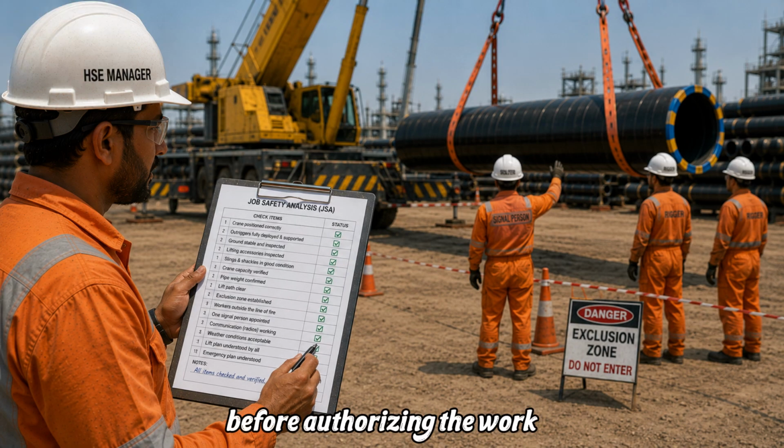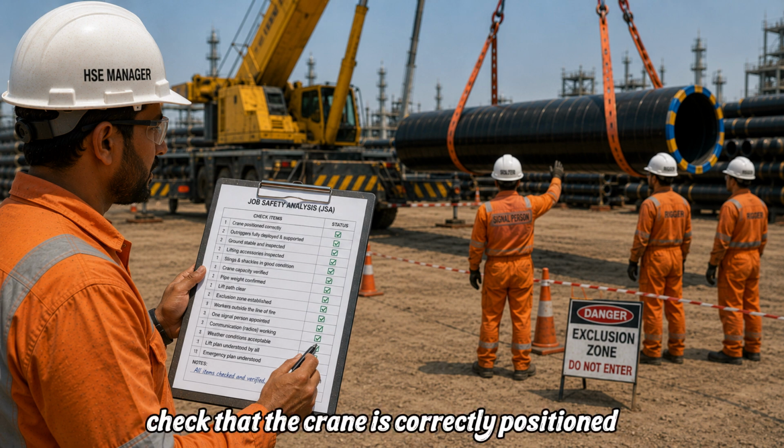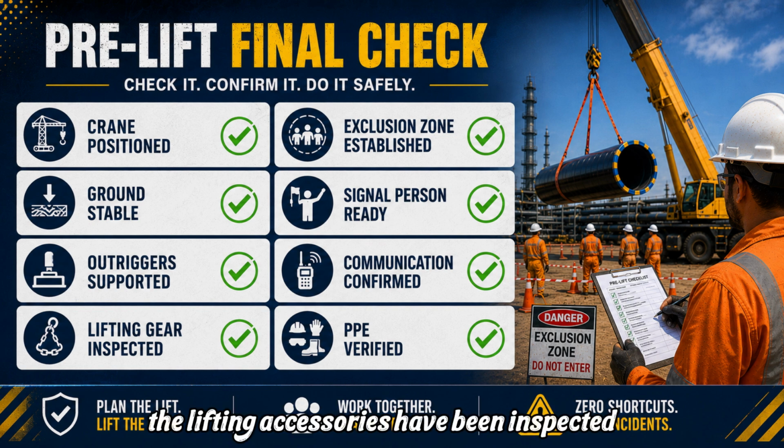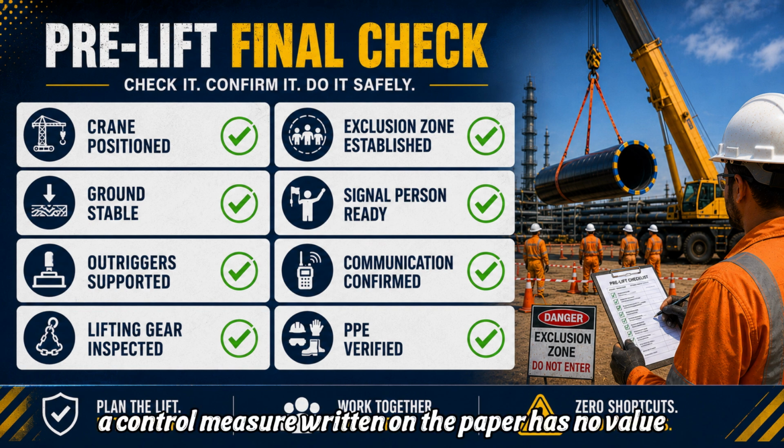Before authorizing the work, verify that every control measure listed in the JSA has actually been implemented. Check that the crane is correctly positioned, the outriggers are fully supported, the lifting accessories have been inspected, the exclusion zone is established, and all personnel are wearing the required PPE. A control measure written on paper has no value unless it is applied in the workplace.